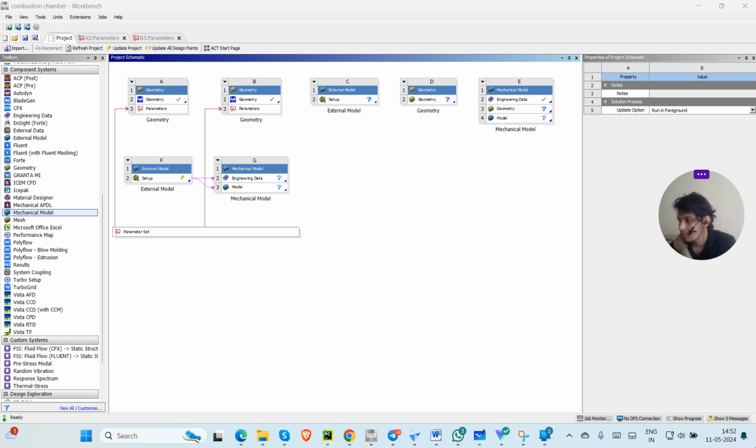For use in Fluent Meshing, the geometry is extruded in the z direction at a distance of one tenth of the chord length, and symmetry conditions are applied to the side boundaries. We will apply far field boundaries at the outer boundary of the domain shown in the previous slide. The simulation result will be compared with test data from a wind tunnel.